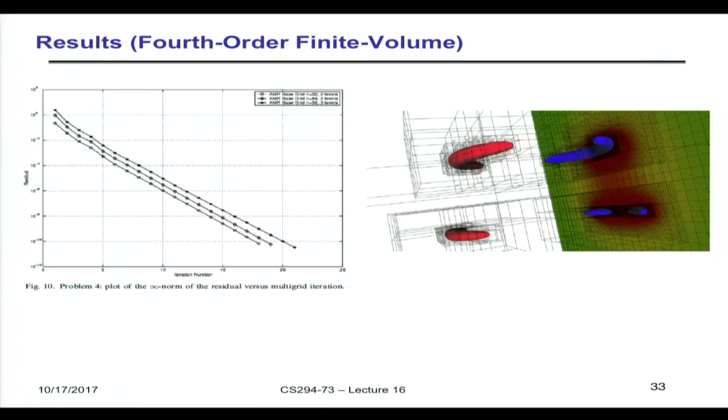Now again, if there's a scaling between the two of them, you're able to look at the residual reduction, but I could give you a starting value and a scheme that would make the residual go up, even though the solution itself was getting better. And then it will settle into its long-term behavior of this kind of nice convergence once you've gotten rid of those initial bad eigenmodes. So don't be discouraged if you see a couple of kinks on the way up to get your problem solved. What you want is that long, quick march versus iteration, and as you double the size of your problem, the iteration count should change only minusculely. Like log n is usually what the mathematics will tell you.